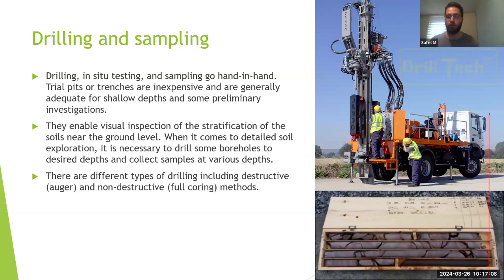The first one, as you're going to use most, is the usual drilling of boreholes. As you can see on the right side, that's one basic picture of how boring actually looks, and there's a bunch of samples that you're going to use depending on the type of drilling. So drilling, in situ testing and sampling go hand in hand. Trial pits or trenches are inexpensive and generally adequate for shallow depths or preliminary investigations. So just for feasibility studies, don't go for a skyscraper design with just trial pits.